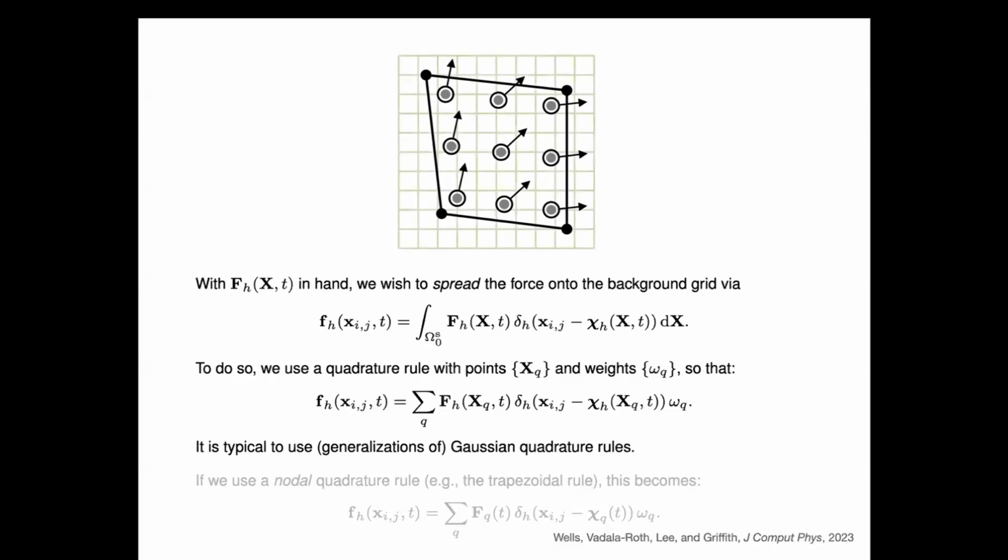When we first put this together, the idea was, oh, I can put the nodes really far apart and not have leaks through the structure just by filling in enough quadrature points in the interior. Then as the thing deforms, you can change your quadrature rule so you have more points or fewer points to make sure that you have a particular point density to avoid leaks.